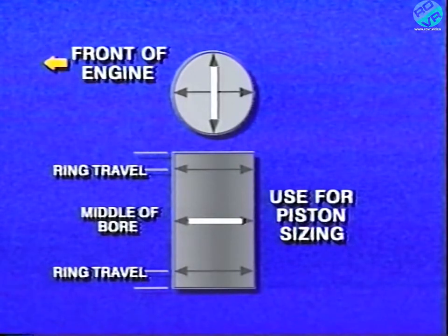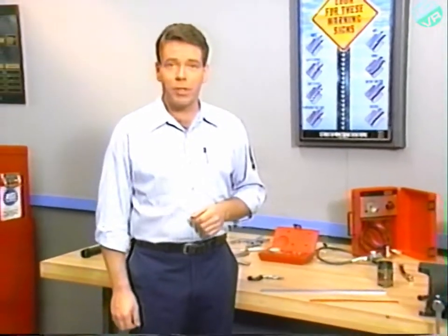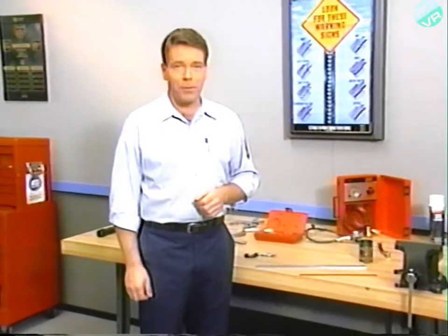Another measuring tool you need to be familiar with is Plastigauge. The Plastigauge method is a system for measuring crankshaft bearing clearances. The measuring technique we're about to show can be used if the engine is on an engine stand. If you're measuring main bearing clearances with the engine still in the vehicle, you'll need to refer to the shimming procedure outlined in the service manual.